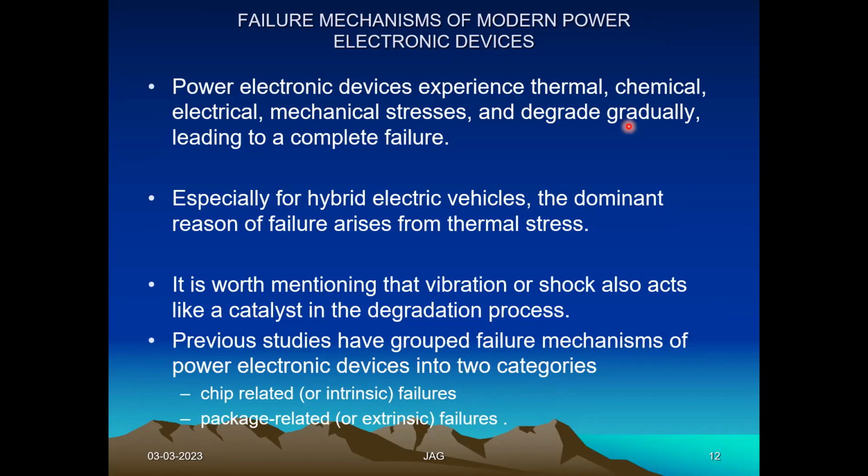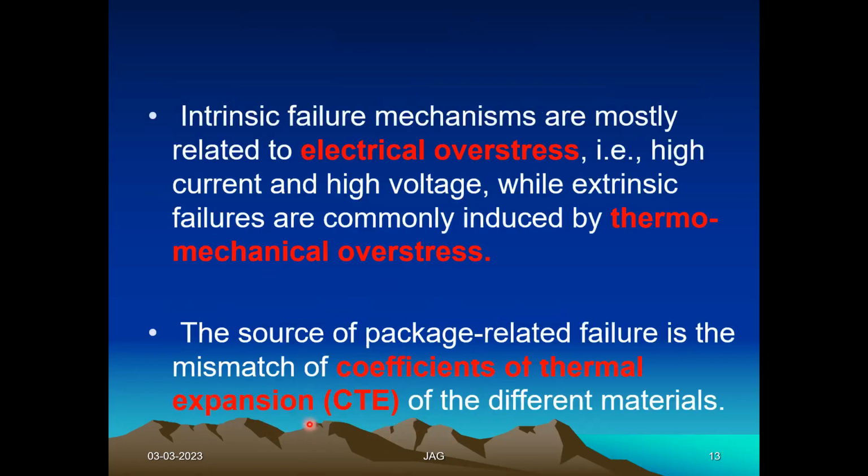So there are two reasons for the failure. One is chip related or intrinsic failure, the other is package related or extrinsic failure. Intrinsic failure is electrical overstress. High current and high voltage are the reasons for electrical overstress. And thermomechanical stresses are the reasons for extrinsic failures.